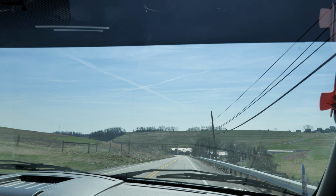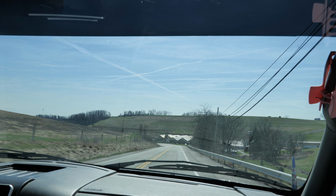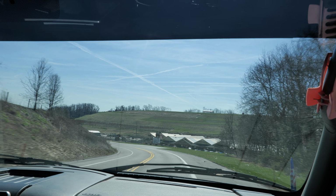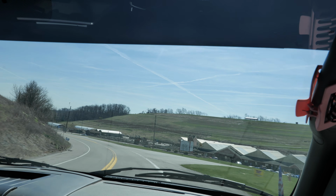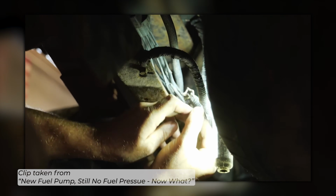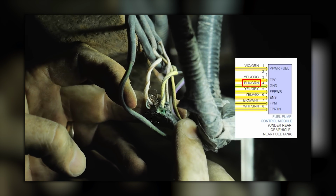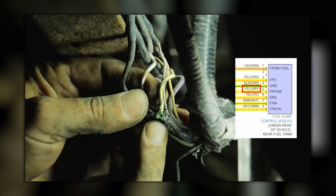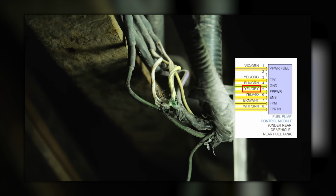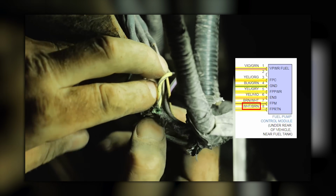I think this is the model that has the fuel pump control module on the frame. Do you remember the one we did? Was it a Ford van where the wiring was all jacked up on the fuel pump control module? Do you remember? I see a broken wire. This has been replaced before. See the green cruddies? Yeah. And then this broken wire here. Yellow with a gray, that's the one that's broken. Yellow gray is our fuel pump power. And then the white and brown looks all messed up too. White and brown is my fuel pump monitored signal.